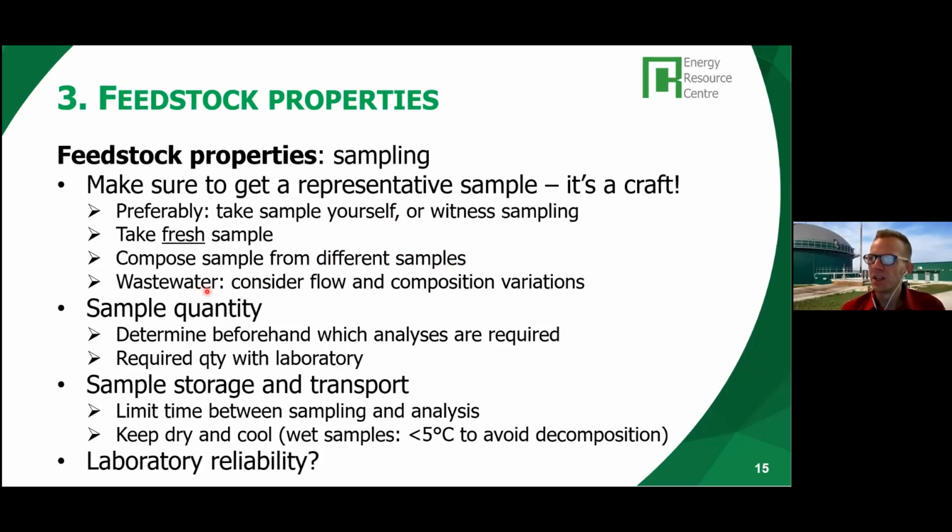Especially with wastewater, it's very important to realize that the composition of wastewater can vary throughout the day. For example, because some of the processes might be taking place during some parts of the day, and others may not, and that's important to consider when you take a certain sample, that it might be different from when you take your sample a few hours later.